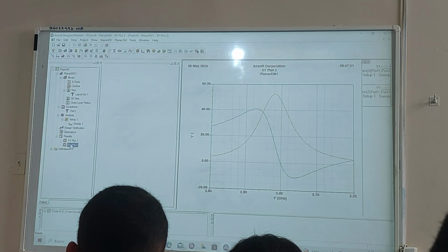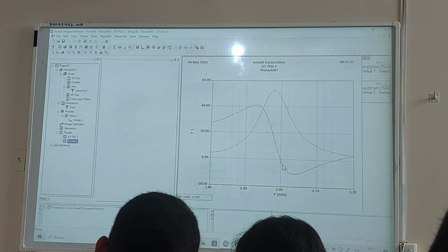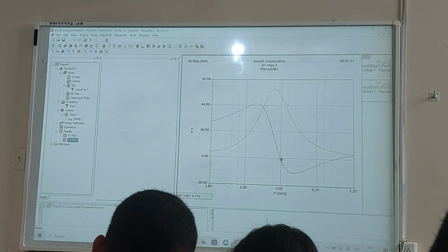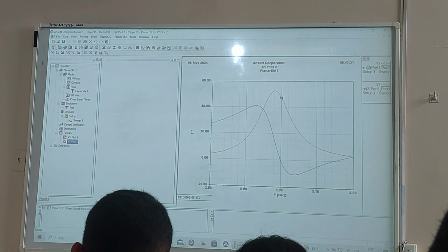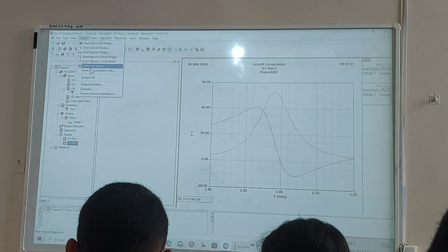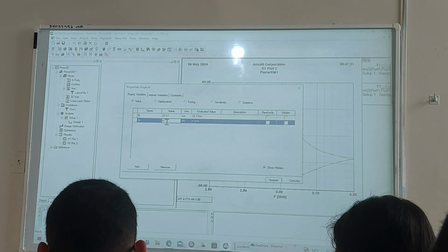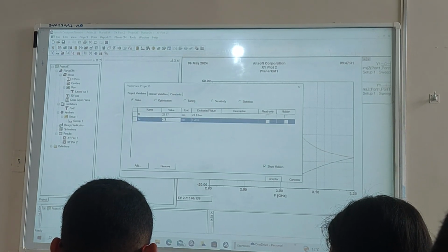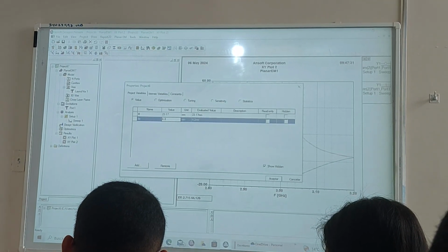And here, if you look at here, you can see that there is imaginary part near to 0, but the real part is not 50, is 47. We want to go to 50. We need to move the excitation to a bigger size, because remember that if we go to the center, it's 0.